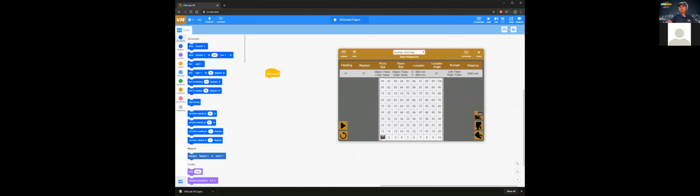All right. Let's go to number 2. Turn for degree. And I'm going to move forward for 200 millimeters. And that should take me to number 2, right? So just test that out. Turn right, go forward. Hit number 2, right? What if I want to go forward more? I just enter the number. Easy, simple enough, right? 400. Now that should take me to number 3. All right, cool. So that's the more traditional way to solve this maze using just only the drivetrain, right?